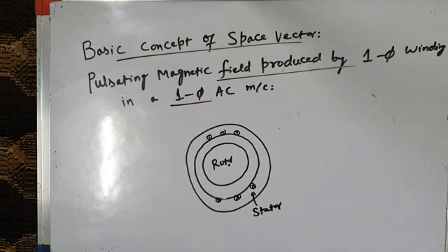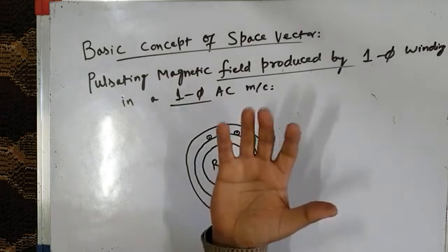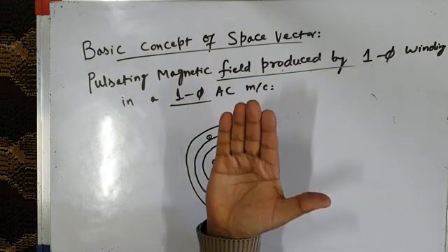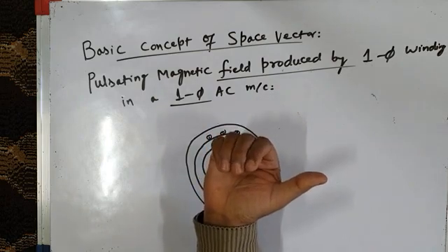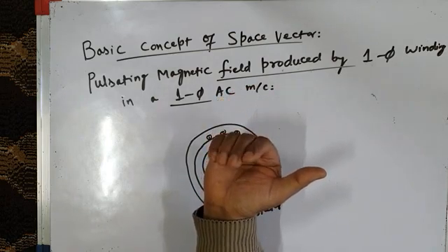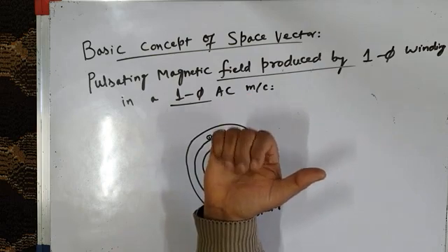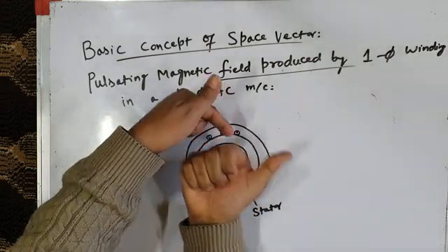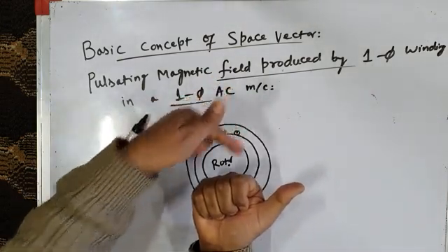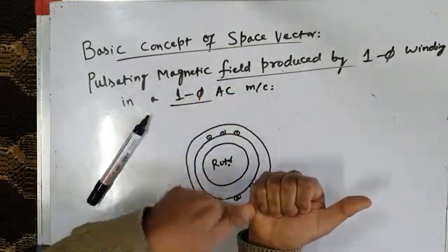Okay. Now these single-phase AC currents will produce a magnetic field, and we use the right hand rule. The right hand rule says that the axis or direction of the magnetic field will be like this. Just curl these fingers. In the top conductors the current is coming out, and in the bottom conductors it is going in.